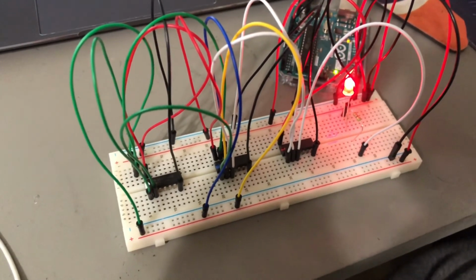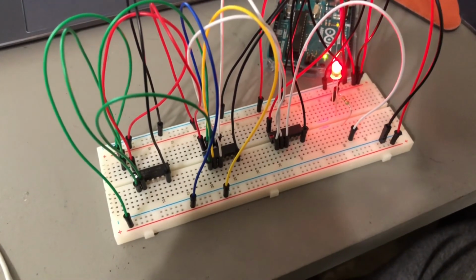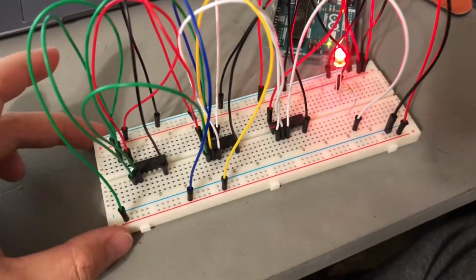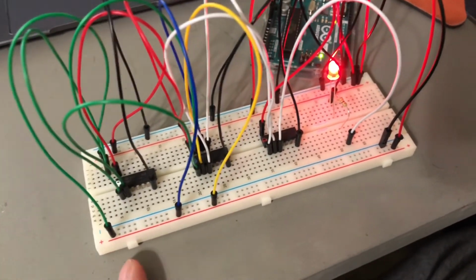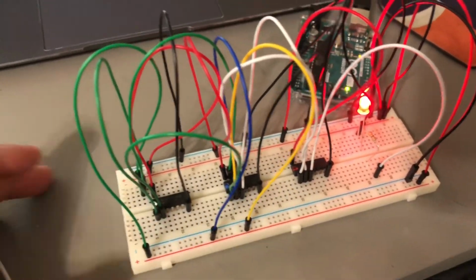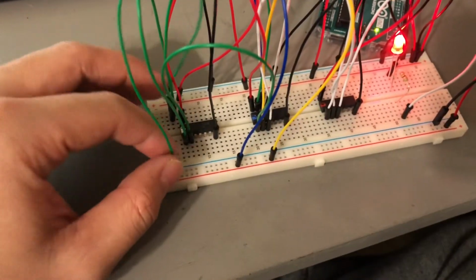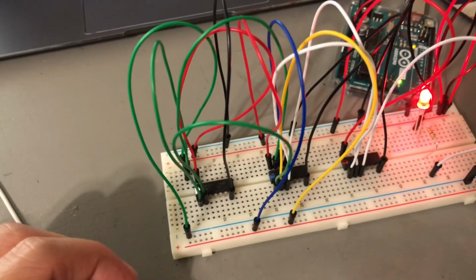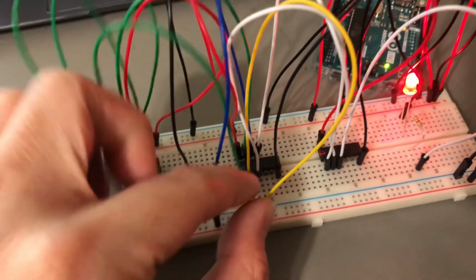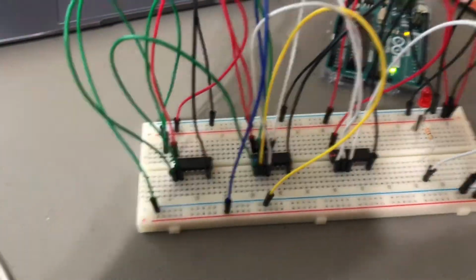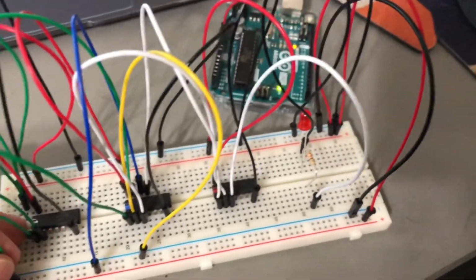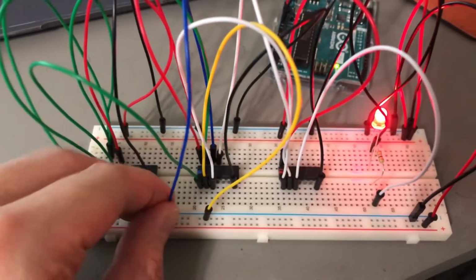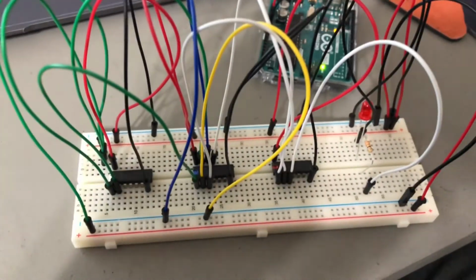Okay, so here we have questions 1 and 2 for the in-lab portion for lab 1. My current state of the circuit is everything is on high state. So I'll go through a couple of the different situations as shown in the truth table here. So this one is 1 1 1 and the LED is on. If I were to take the selector wire and bring it to low, it's still going to be on. And if I were to take the selector wire and A and move it to low, you can see that the LED turns off. And the same would go for selector wire at high and both A and B at low, the light is off.